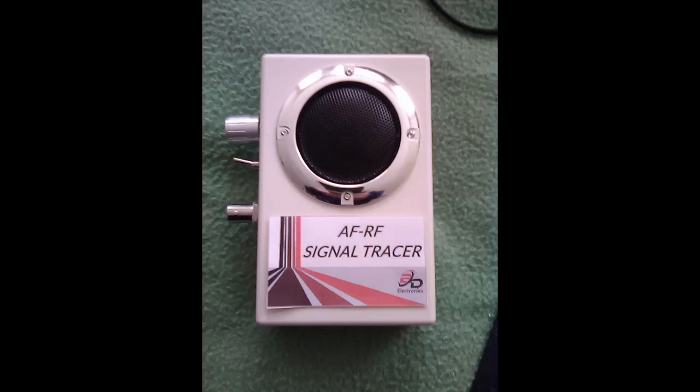But then another of the beta testers found that when you connected the test lead to certain parts of the IF chain, it was really loading the circuit down. And so I started experimenting around. I found that just the act of connecting the coax, even if the coax wasn't connected to anything, was loading the circuit down. I measured, and the coax acts like about a 200 picofarad capacitor, just shorting the RF to ground.